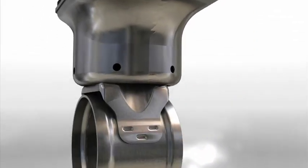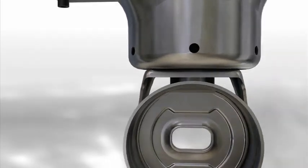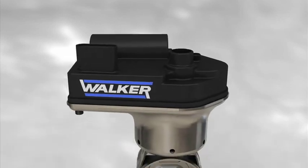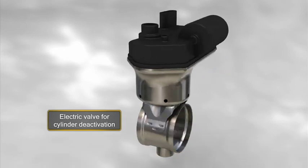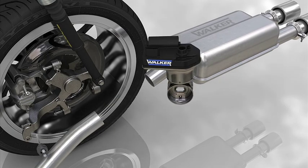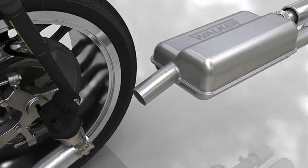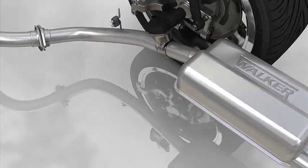To solve this problem, Tenneco has designed an electronic valve to control back pressure that not only works on vehicles equipped with conventional engines, but does so in a particularly effective way on engines fitted with cylinder deactivation technology. Its operation is very simple. This electronic valve is integrated in the car's exhaust pipe before the rear silencer. The valve is controlled by the car's electronic control unit, ECU.